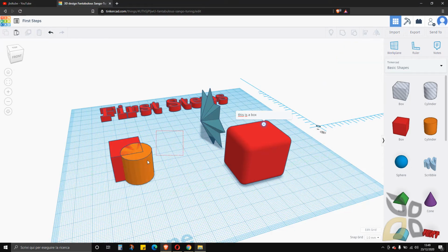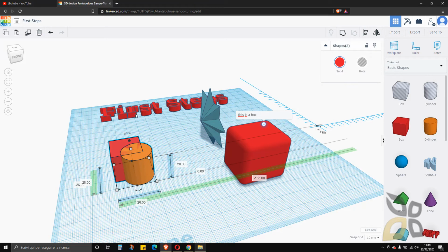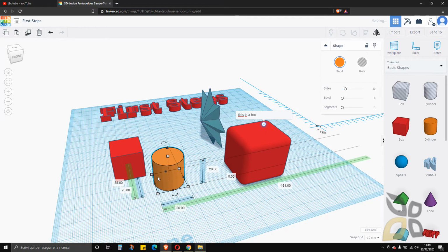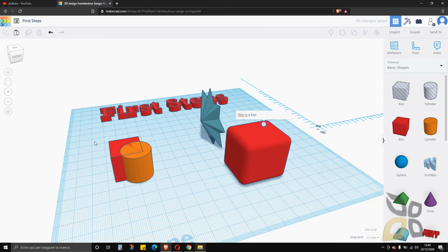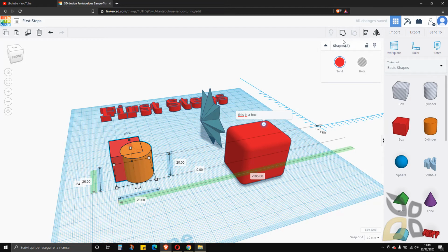So click and drag with the left mouse button to select more objects, and then I can create a group right here, or Control G, and there you go. So look what happens. This becomes a completely unified object. Also, I can ungroup this, and I will have those two separate entities back. Again, let's make it together, and this time, basically now I am unifying this by creating a group.